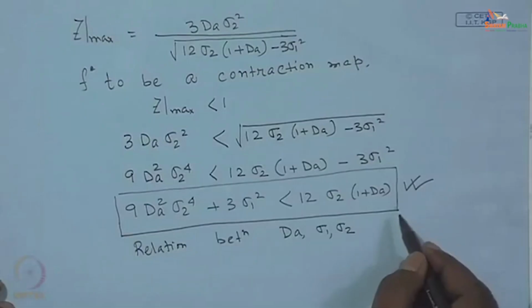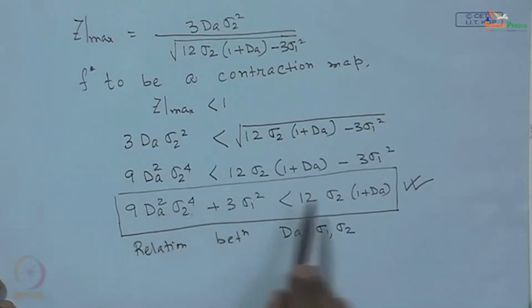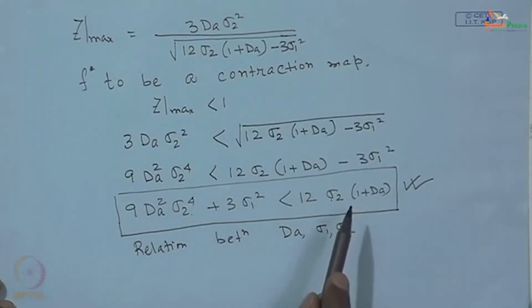And for the last problem, the generalized rate expression, this is the relationship between the parameters sigma 1, sigma 2 and Damkohler number. So, you have to select Q and Cf, these are the actual operating conditions you are controlling as an operator. On the other hand, these kinetic parameters K1, K2 and K3 are fixed by the rate expression, you do not have much control over them.